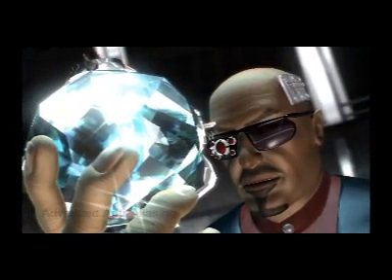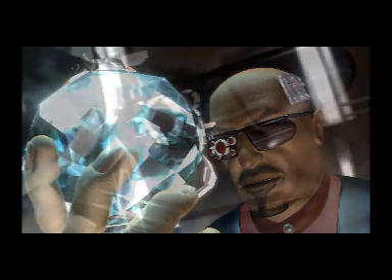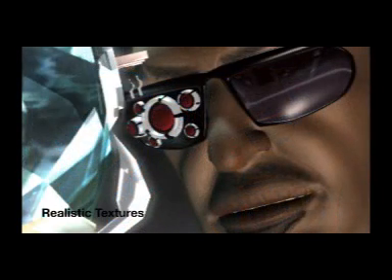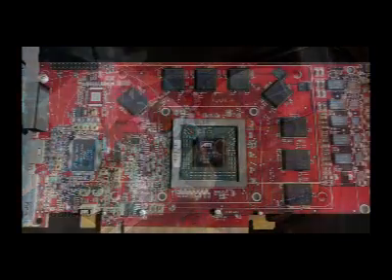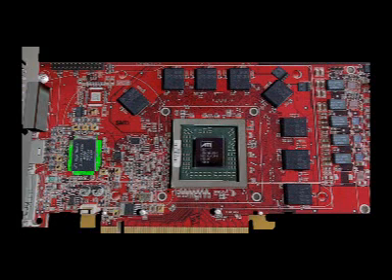This yields 64 gigabytes per second of memory throughput, up from the 49.6 gigabytes per second found in the ATI Radeon X1900. The ATI Rage Theater companion chip delivers video input and output. Importantly, the X1950 XTX is one of the first cards to include HDCP support, an important capability for anyone looking to play back high-def protected video under Windows Vista.